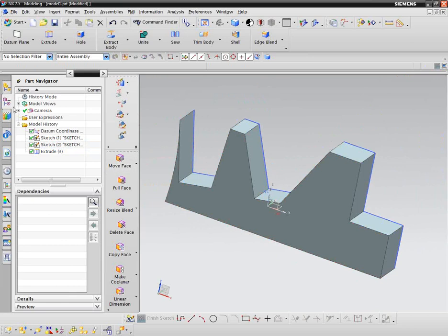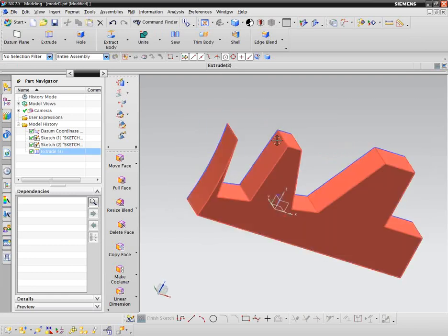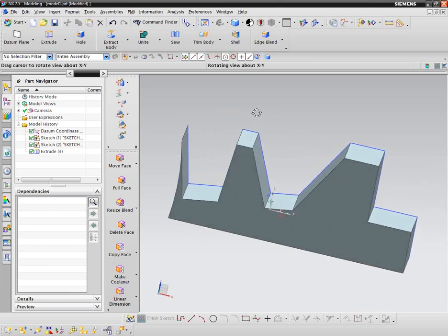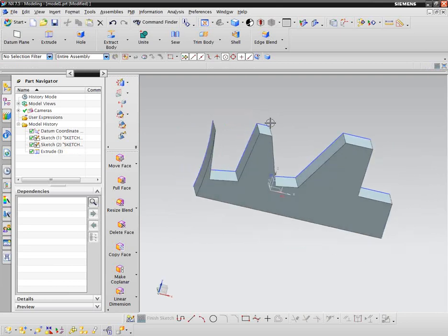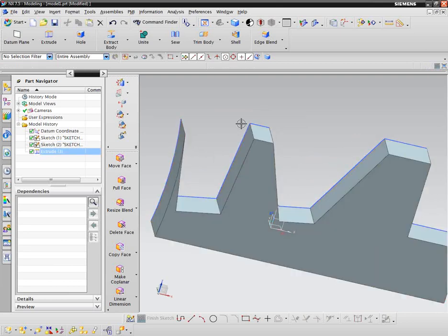That's the beauty of designing in NX 7.5, but we have to go on to the blending. So a three-phase blend, essentially what the purpose is to make it so that you can fit the same profile without compromising or trying to figure out what, because right there you have an edge, and then on the other side you have an edge. You might have different radii that constitute what really fits there and how well they're going to fit together and whether they fit together smoothly.